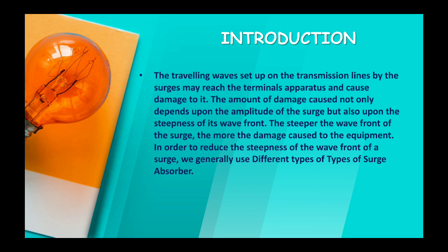If the steepness of the waveform is increased, then the traveling wave effect is also increased. So the steepness of the wavefront has to be minimized with the help of surge absorber.